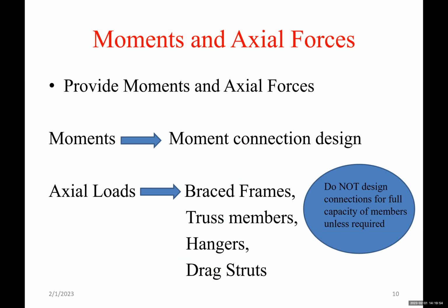Moments and axial forces: provide moments and axial forces. So if we have not only shear forces on the reactions or in the members, if we have moments and axial forces, add those, because they also will need to be designed for. The connections need to be designed for moments and for axial forces, and of course for the combination.